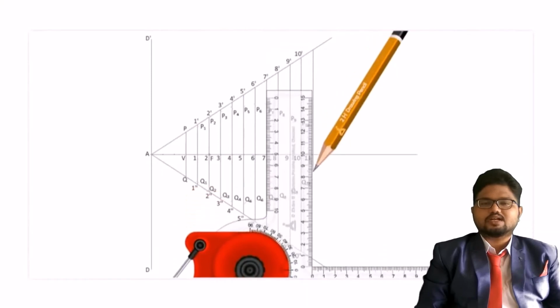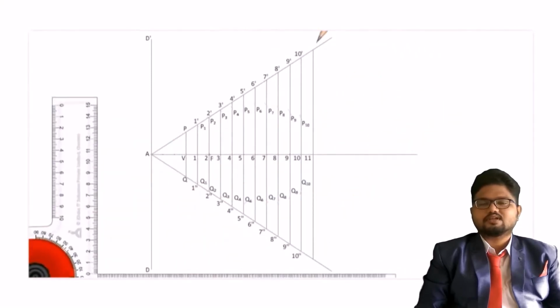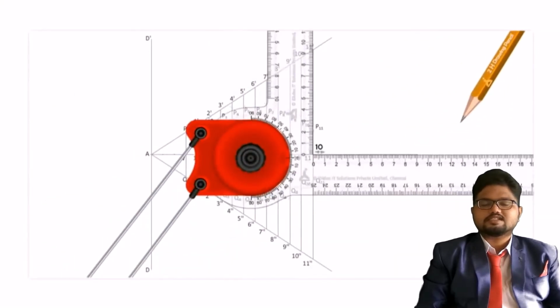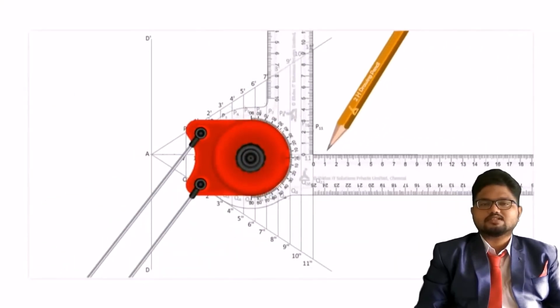So in this way you continue to go up to 10, 11, 12 until the curve has been closed. So I have taken 11 dash radius, F as center. It is nearing P11 and Q11. So now lastly we have the 12th point. The 12th point is drawn the same as usual, the general method.